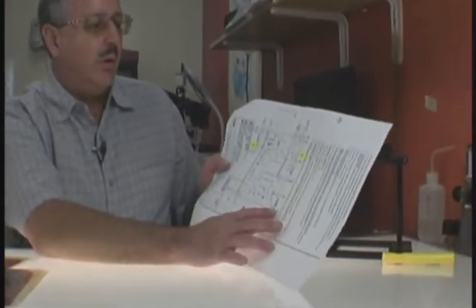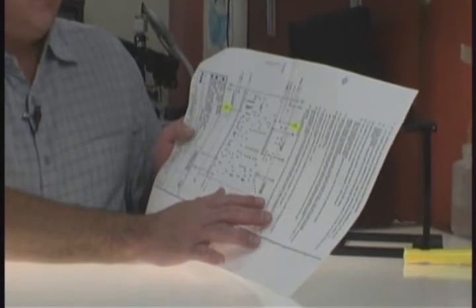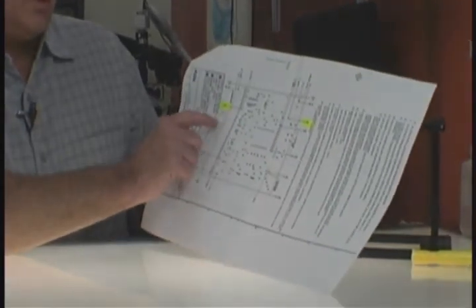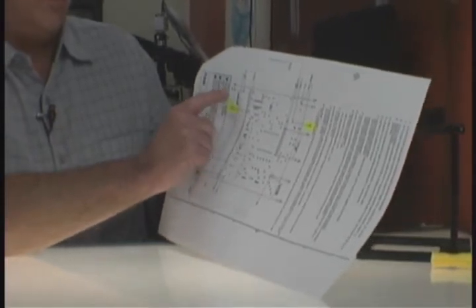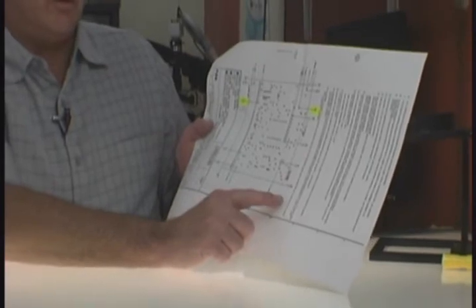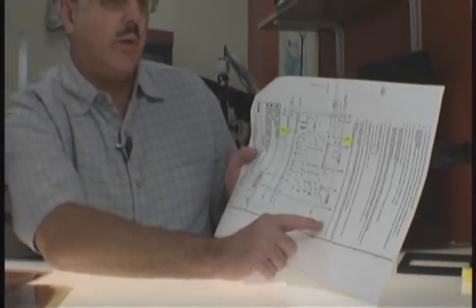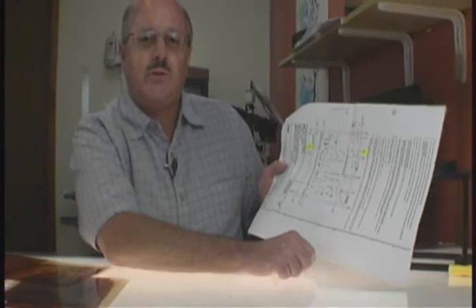The next step in the process is to inspect the drill if one has been requested by the customer. What we do is we make a copy of the customer's original print. We use that for inspecting the drill, and any defects that are found are highlighted and notated on the copy of the print. Those defects are numbered, and the number is placed in the lower right corner of the print so that, again, the operator knows how many defects he needs to find and correct. After the drill check is finished, the job is returned to the operator for corrections.